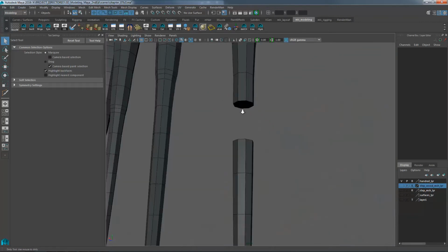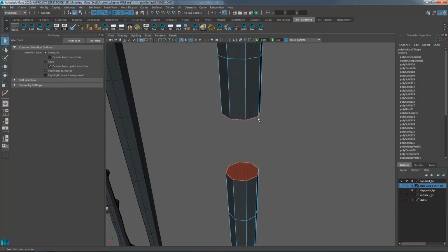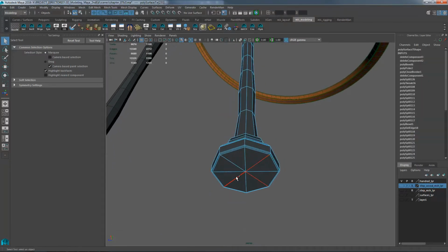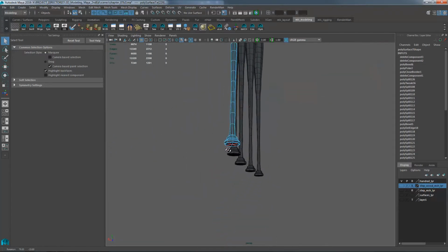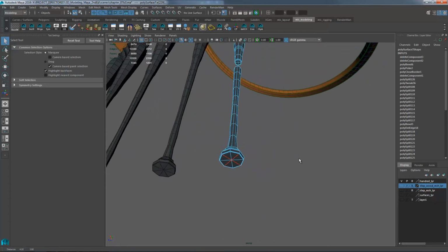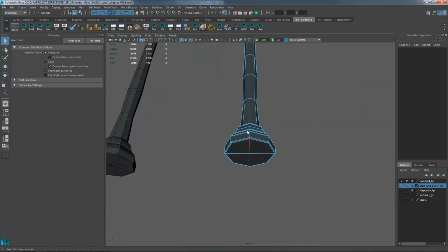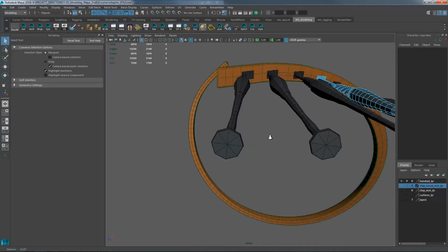Right, just hide the steps to make it a little easier. Select n-gons, poke faces, and so on and so forth. We are dealing with an 8-sided cylinder here, so take the time to remove every other edge. That should be good. So when the time comes, if the time comes when you have to smooth it, everything will be quadrilaterals. I should have done that the first time.